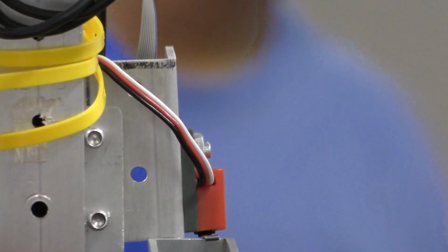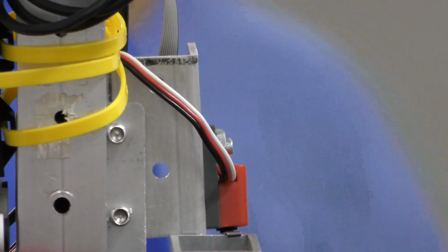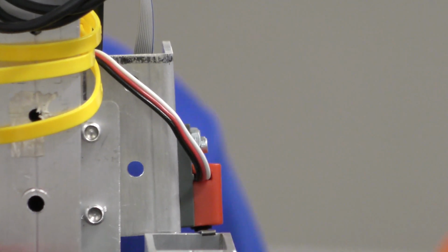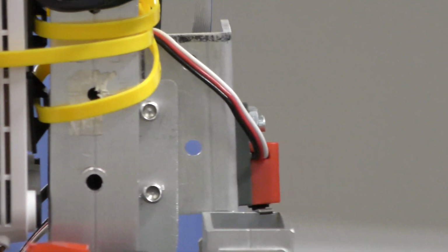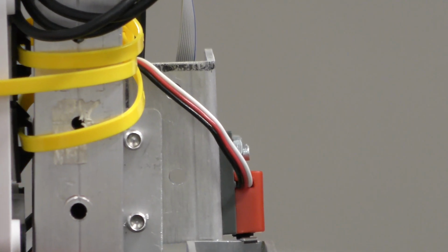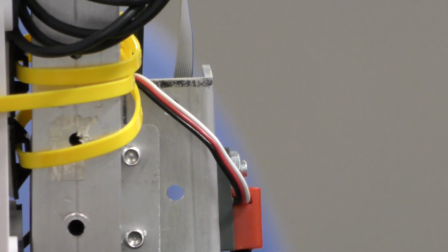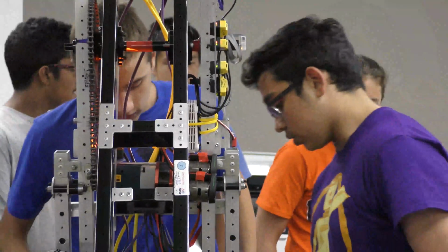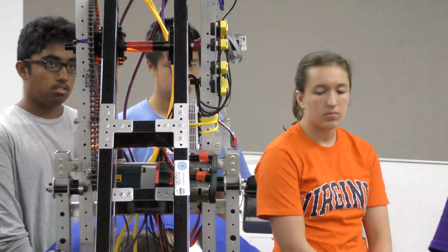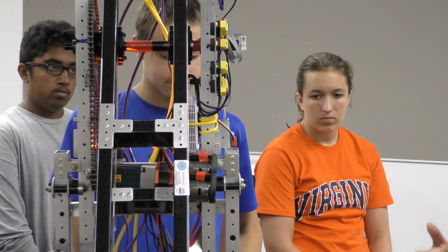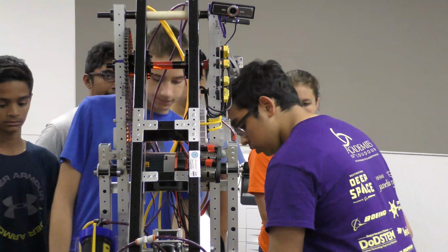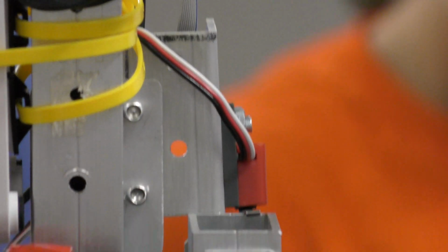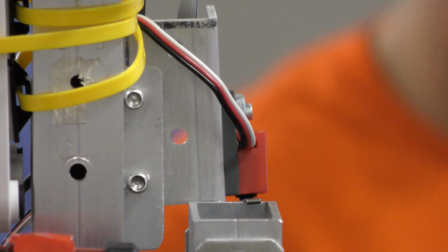So what's the thing that controls all the columns again? Is the CAN connected to only one port? On the Rio, yes, there's one CAN port because it's a network, and you have every device connected to that network. But digital input is not connected via CAN, because it's not using any of the Talons. It's plugged directly into the RoboRio.